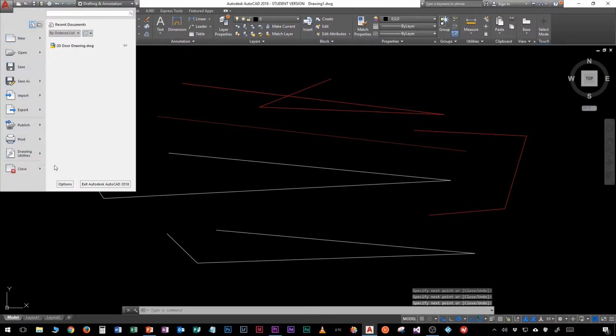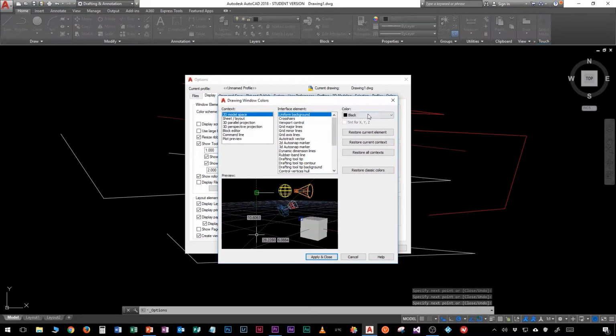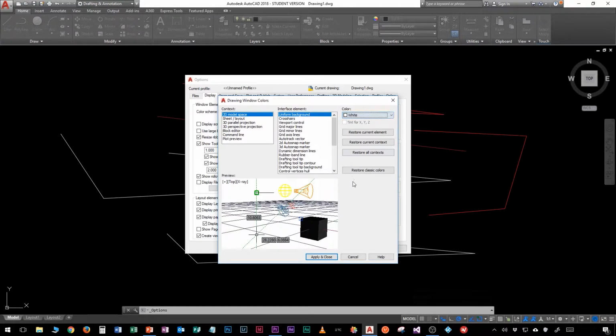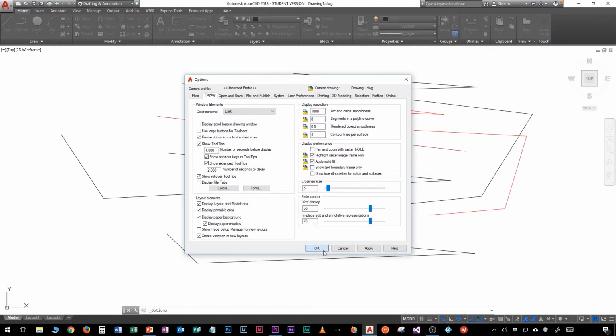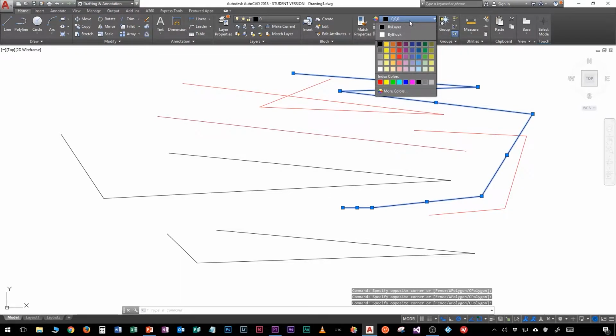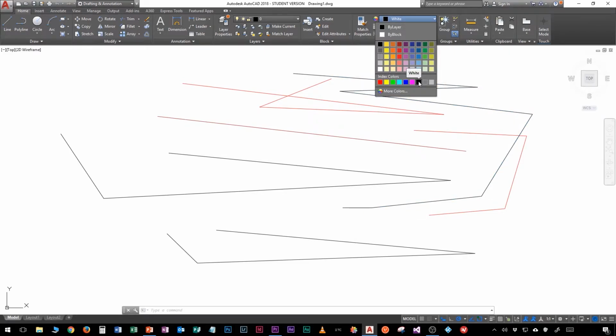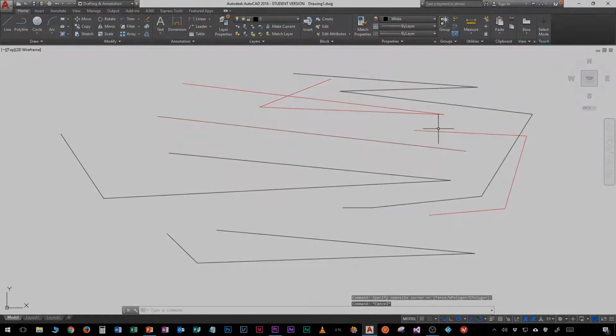So I'm just going to change my background to being white again. And you can see that that line did actually draw, it's just that it's not actually set to a special colour that will change depending on the background. It's set to a value of 000 on the RGB. So remember that you need to use the index colour 7 in order for that to change.